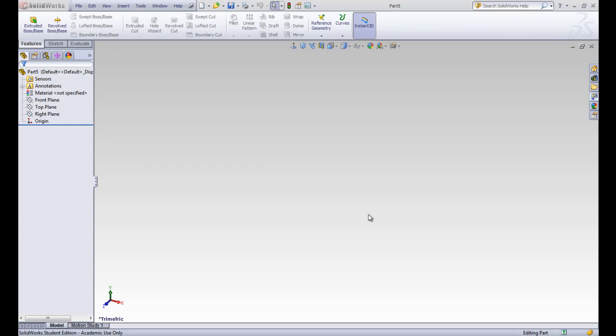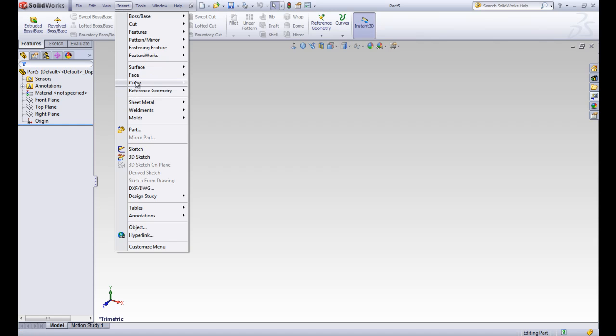This is SolidWorks tutorial lesson 3.4. In this lesson we're going to use the sweep tool to build a spring. So we're going to start by going up here to Insert, and we're going to insert a Curve and a Helix/Spiral.